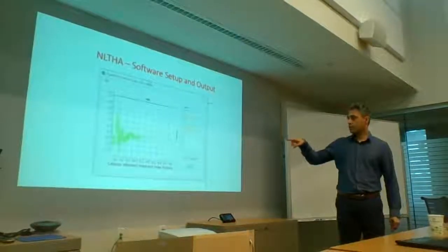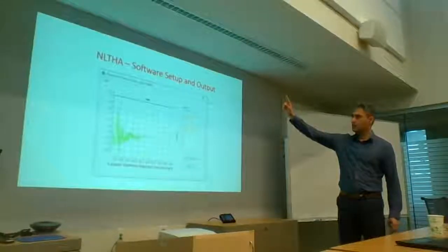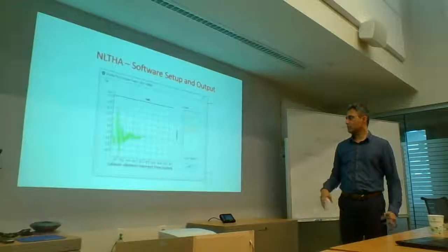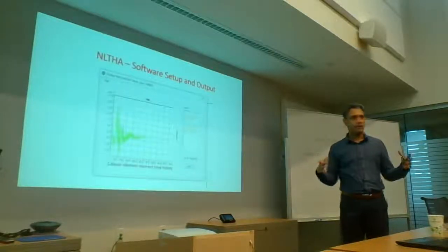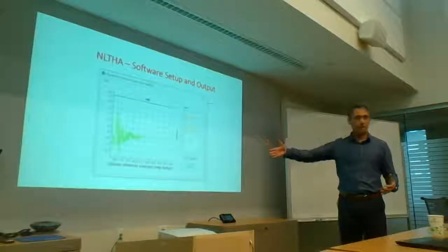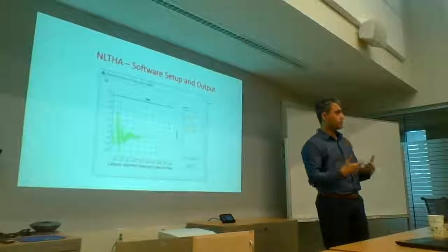This is the Caisson moment time history, and you can see it jumps from 15, 16,000 down to about -6. Even though these caissons had no rebar, they were just ginormous, so even their cracking was much higher than this. So once we did this, we were fairly comfortable that the caissons weren't going to crack.